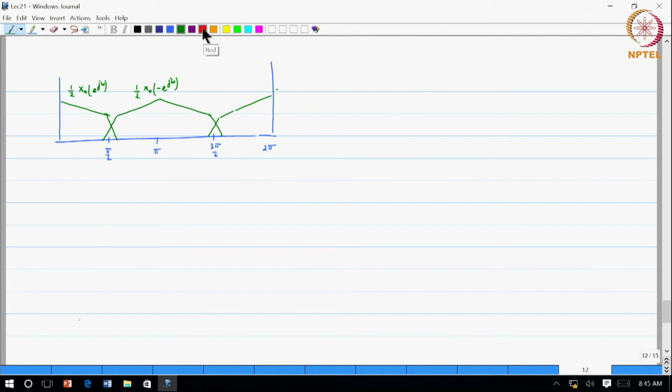Onto this I am applying F0 of z. So, F0 of z is a low pass filter, which will have some response of that type. So, the first copy of the signal goes through, that is what we want. It also picks up a portion of X of minus z, that is where the problem occurs.